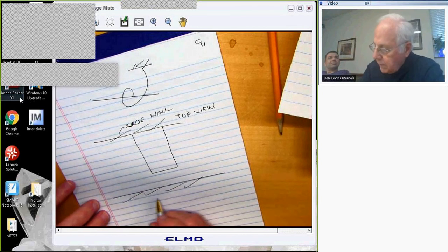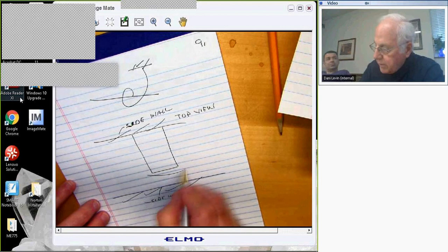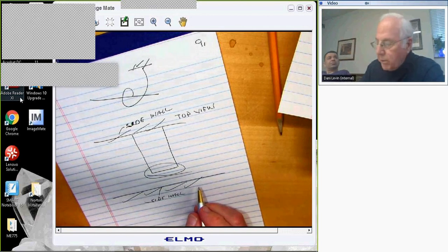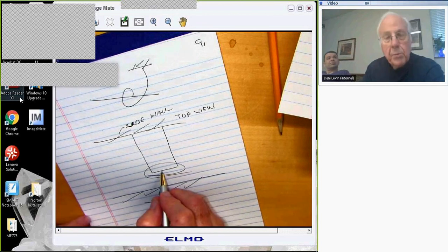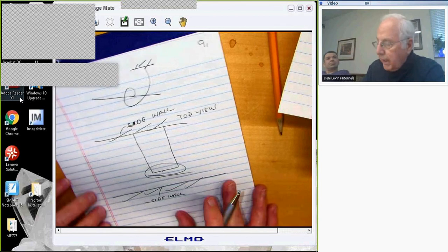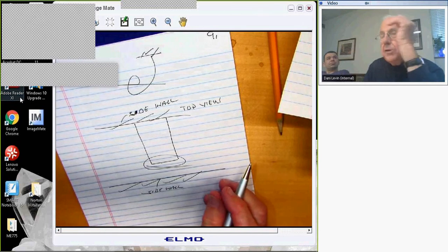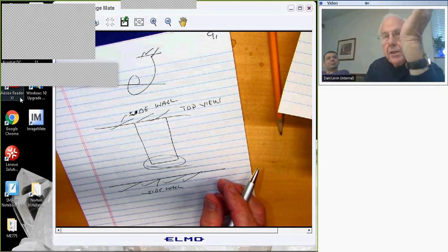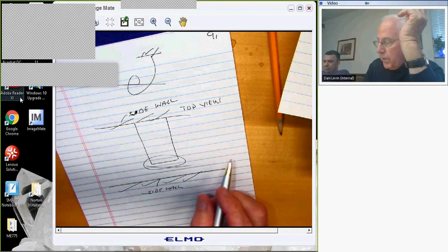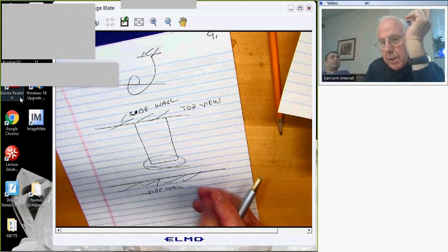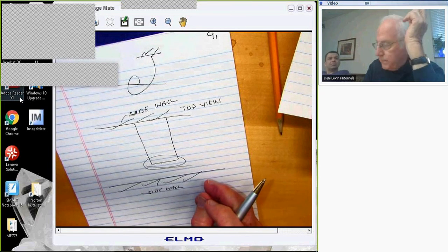And yes, the aerodynamics at this tip will be important quantitatively, and you're right. With a finite aspect ratio, the 2 pi factor will be less than 2 pi. It'll be something less than that. And again, if you have an appropriate aerodynamic model, you can model that as well. Yeah, absolutely. Okay, thank you.